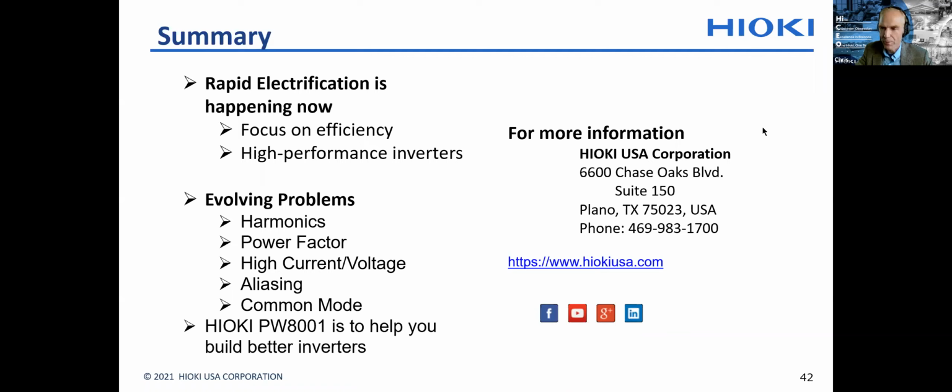We mentioned 5 of the main challenges. That is harmonic content. We see much higher switching frequencies, and we see more harmonics. Power factor is becoming an issue, like Barry showed. The motors start looking more like inductors when you go to higher frequencies, which makes it more sensitive to measurement errors in the current. We have to deal with high voltage, high currents.